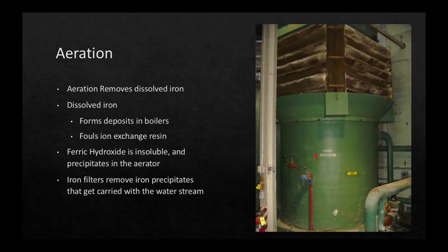I wanted to show you this aerator here. This is at the generating station where I used to work, and like I said, we had a fair amount of dissolved iron, and that was a real problem. It formed deposits in boilers, yes, but the big thing for us was it fouled the ion exchange resin. So we had a demineralizer bank in our plant, and this would have just wrecked it.